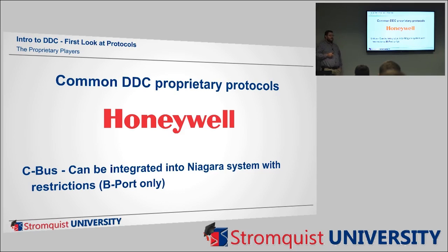It's great when you come in and they have a BACnet controller, and I can say, yeah, I can pull that data in. Anything exposed on the BACnet, any points that I can discover off the BACnet, we can pull in and do a graphic for. But if the customer comes back and says, 6 months down the road, I need to make this slight change in the sequence of operation for this program, you'd have to replace the controller or call in the company, the branch company that is the only one that can program that controller. So there's different levels.